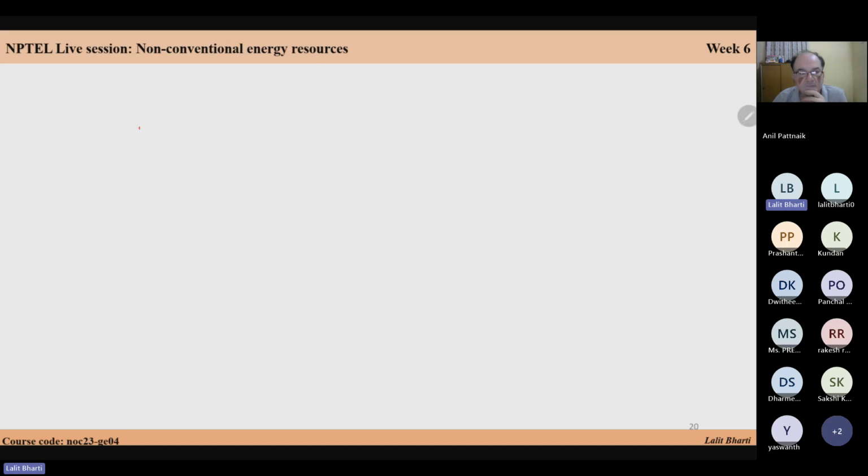Wind velocity 20 kilometer per hour, then the tip velocity is 60 kilometer per hour. Is this right or wrong? So you need the TSR value, or the lambda value, for that. Which kind of windmill? Any specific windmill?